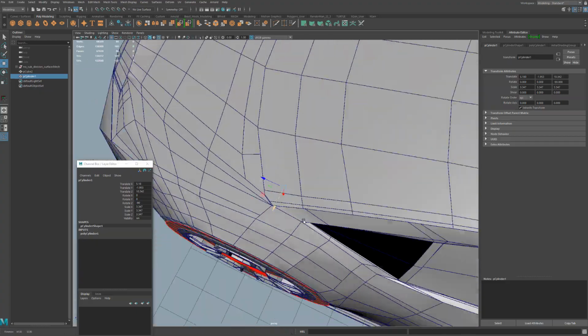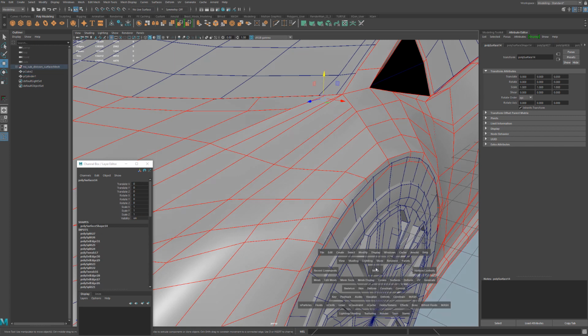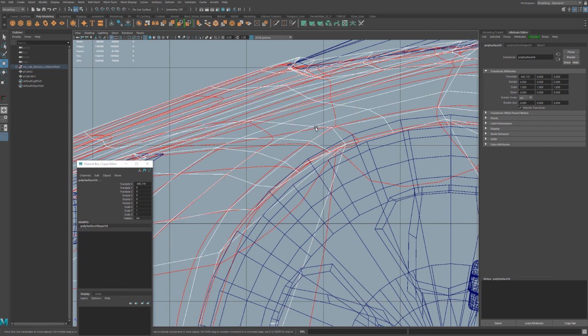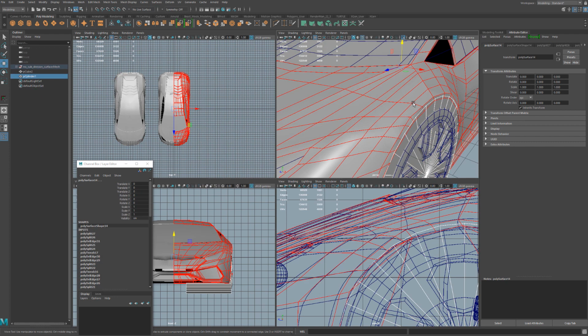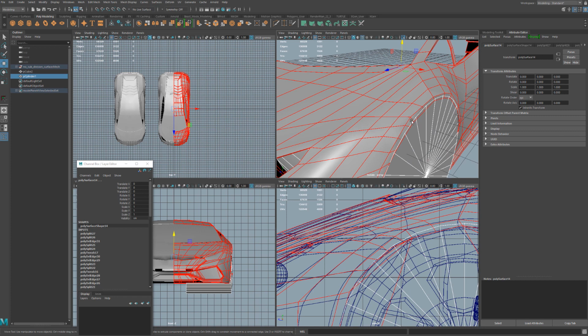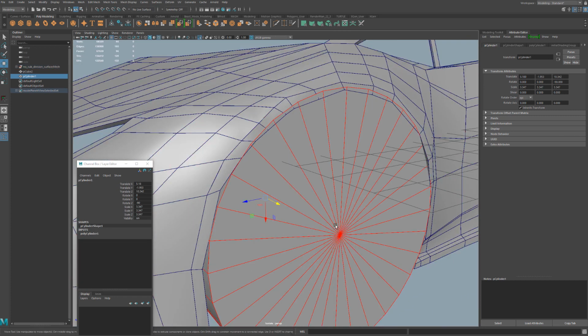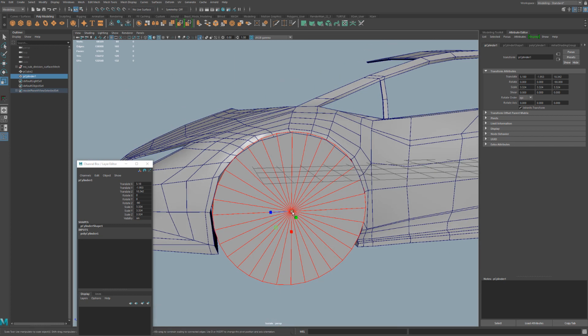And then now what we could do is actually start vert snapping here to get the right spacing. So I'll take both of these pieces. I'll do Shift I. So what I'll do is I'll take my little template here, and the piece that I'm working on, I'll hit Shift I. What I also want to do is move the pivot here, and then just scale this down a little bit to roughly get the right shape of this.